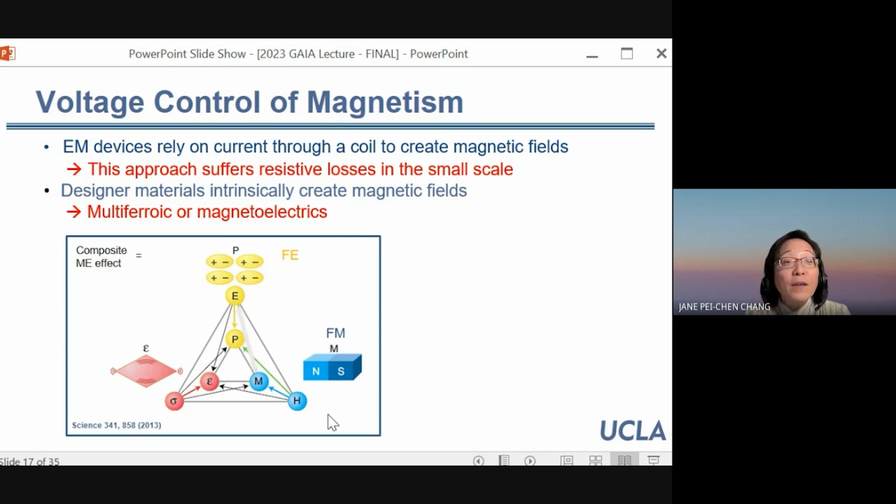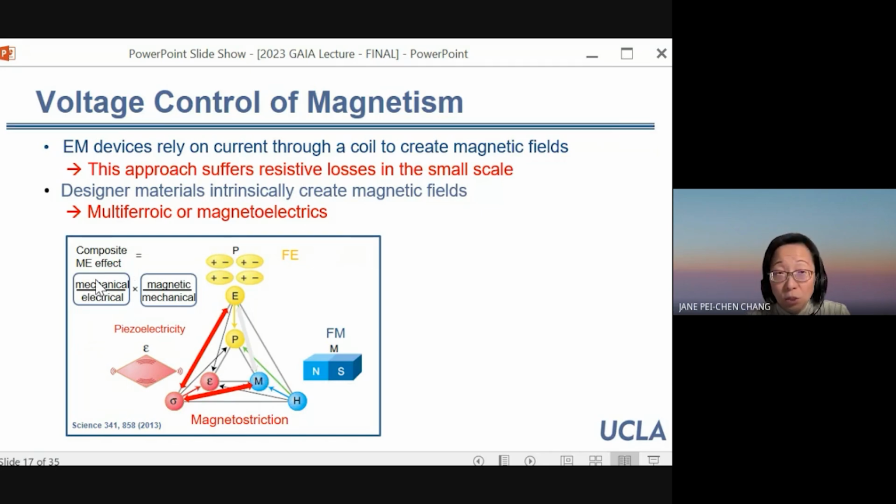But nature gave us a lot of piezoelectric material and magnetostrictive material. So if we cannot get from this place to this place in one straight line, we can take a detour, right? We use the coupling from the electrical to mechanical change, which is a stress or strain, and then transfer that strain into a material that has magnetostriction so that the magnetization can be switched. This particular process required us to design materials, literally with multi-layers that bring different property together through close interface coupling to enable this strain transfer.